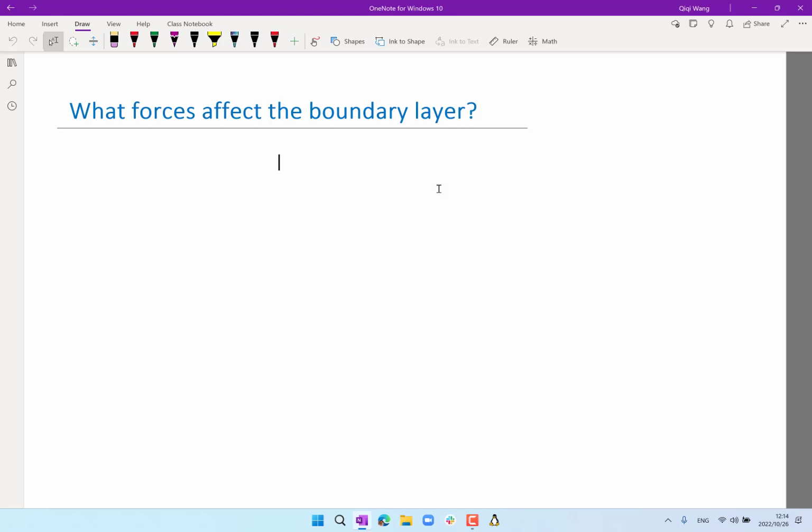It's not simple, because the pressure force does two things. It accelerates or decelerates the flow, right? If there is a pressure gradient in the direction of the streamlines, it can also turn the flow if the pressure gradient is orthogonal to the streamlines. So there is a lot of things to think about, but the advantage in a potential flow setting is that we can use Bernoulli, and that actually simplifies the effect of pressure a lot.